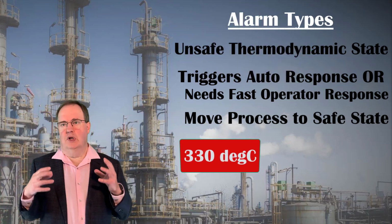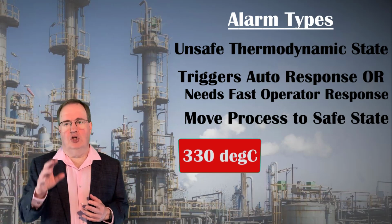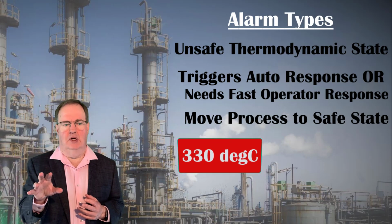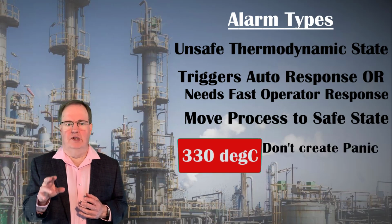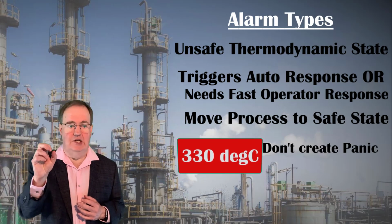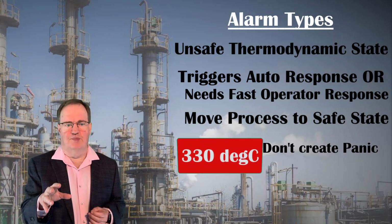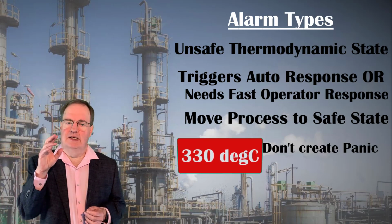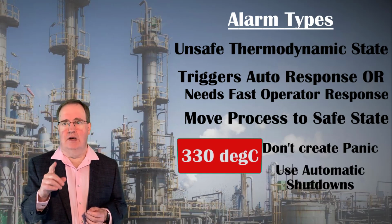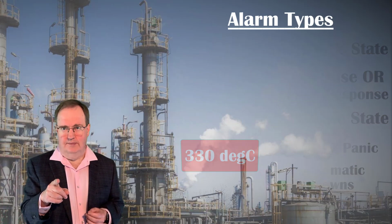These are the alarms where blinking red lights and audible alarms are justified, but go easy with the audible alarms. Once alerted, no operator is helped by having a loud horn going off as he or she is trying to manage a crisis. Give them a silence button. A safe process is one that shuts down automatically, not one with 5 horns ready to blare.